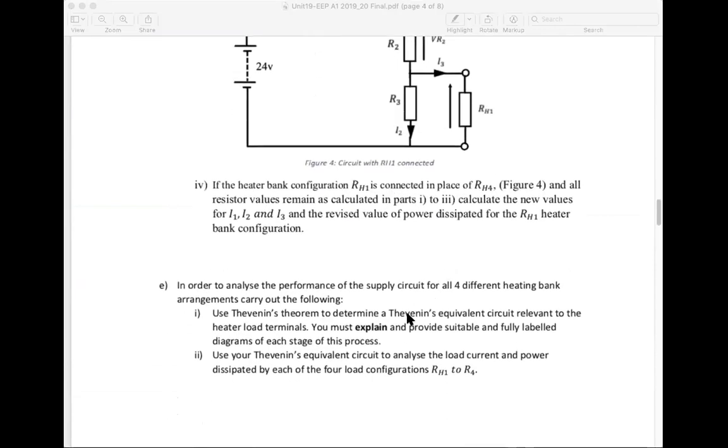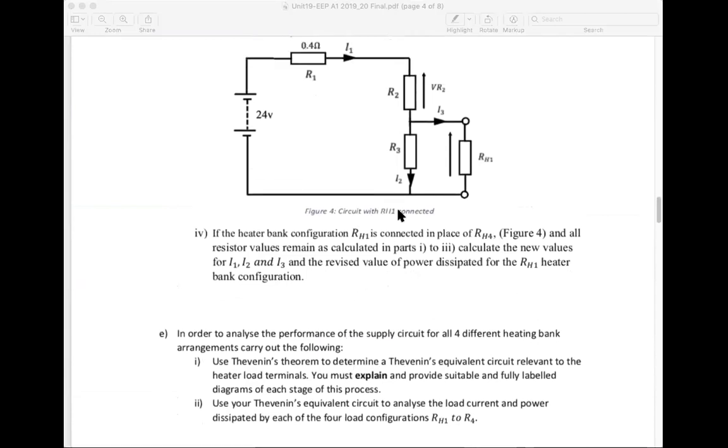So part A is asking you then to go on and use the Thevenin's process on this circuit. So remember what Thevenin's is. You disconnect the load resistance, which would be this resistor here, leave two open terminals A and B, and then you calculate the open terminal voltage, and you calculate the resistance looking back in here. I think we have a handout that's literally identical to that question. Quite close, anyway. That will help. We've certainly done examples.